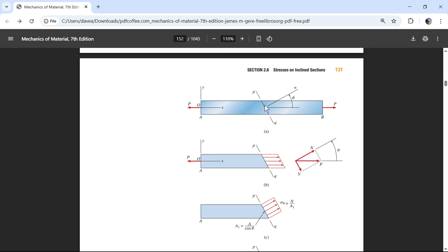At a 45-degree angle, what we'll have is a shear force that's 70% of, so yeah, this is kind of interesting. The shear force will be 70% of 58,000, but the area that it's operating on is 1.4. So this 70% is square root 2 divided by 2, and this area is square root 2.